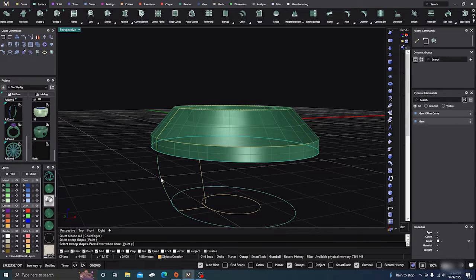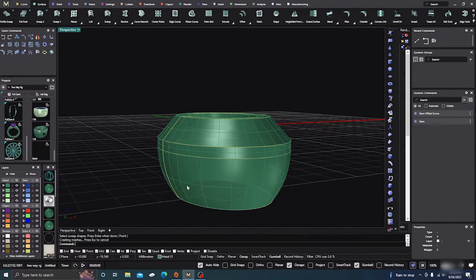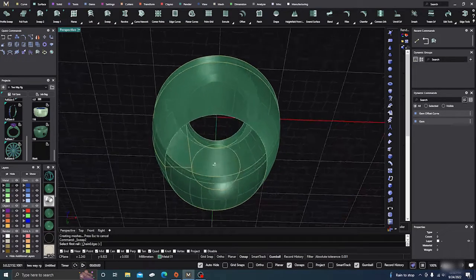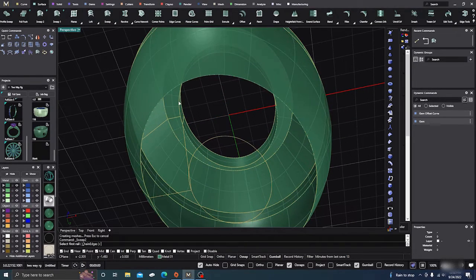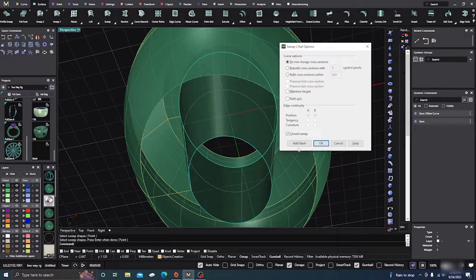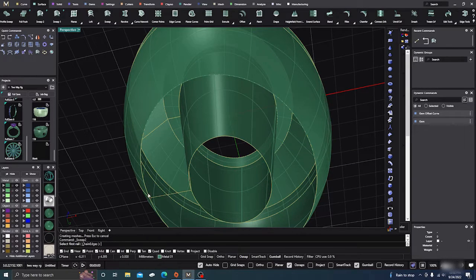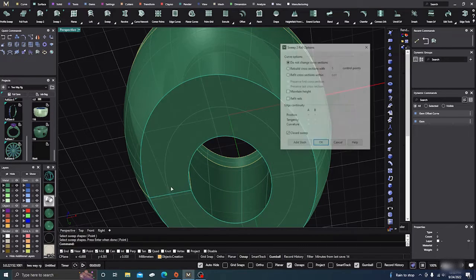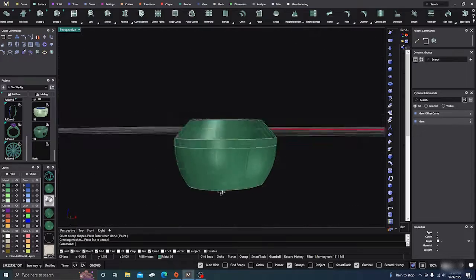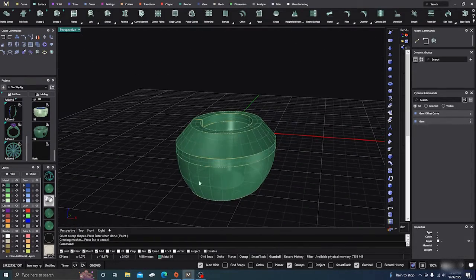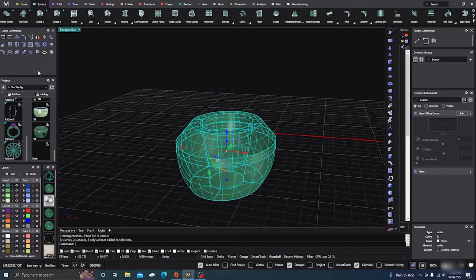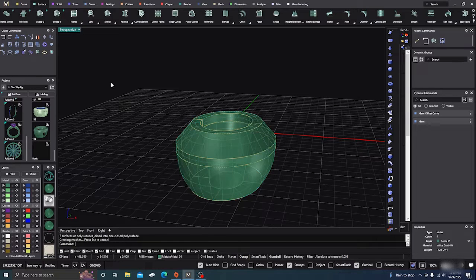And then this rail and this little arc curve, and hit enter. Then go on the inside here, go up to my top, click on this bottom one, this thing here, and hit enter. And then one last time, this rail here and this rail, and enter. So we should have a closed poly surface after we join everything together. We'll take all green and join it together. Here, closed poly surface, so we're good to go.